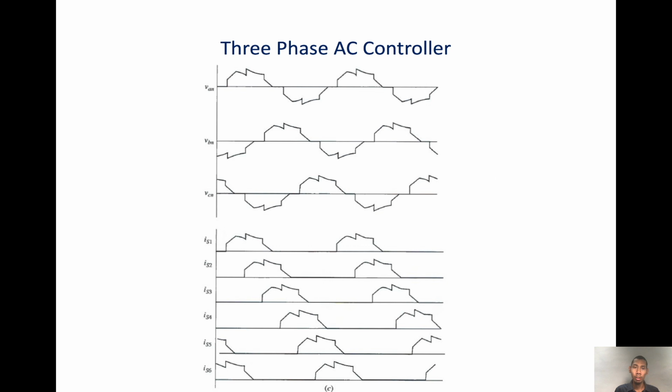So to check the sequence here, this is thyristor 1 on at firing angle 30 degrees. But previously, before thyristor 1 triggers, we can see thyristor 5 is still on and thyristor 6 is still on.